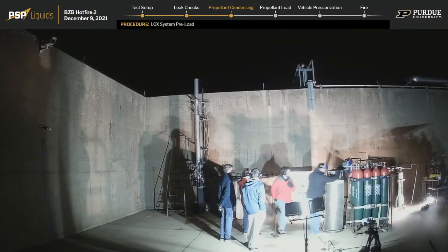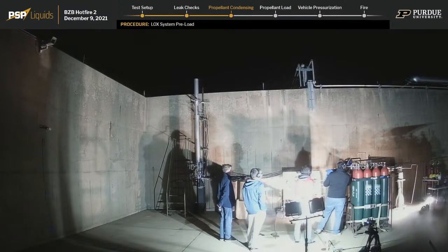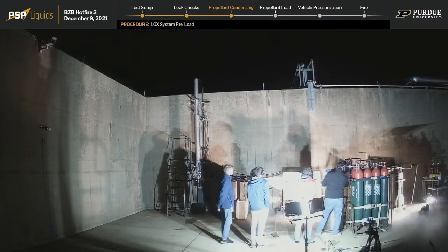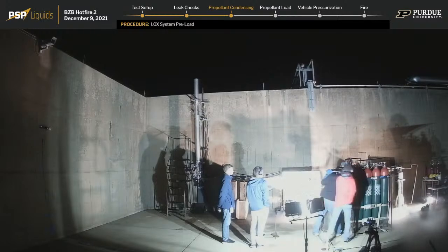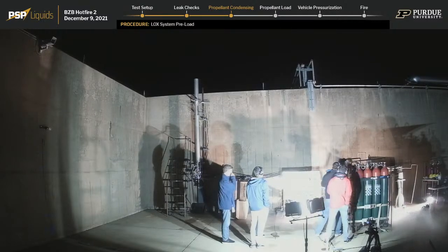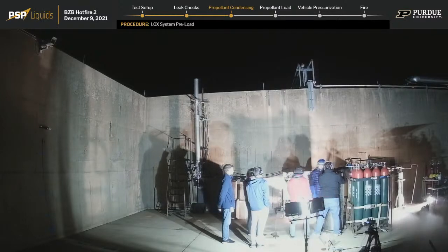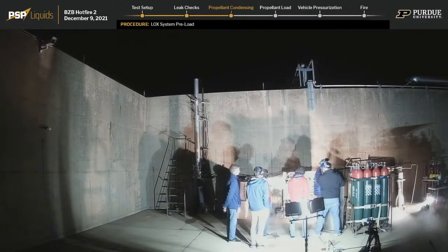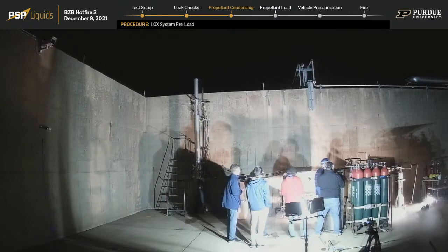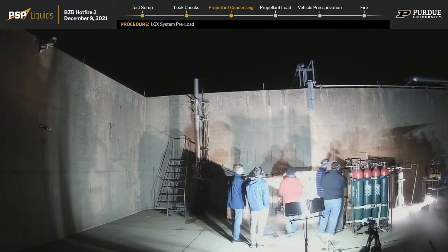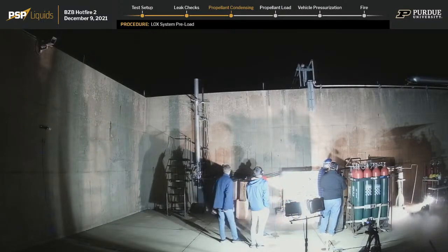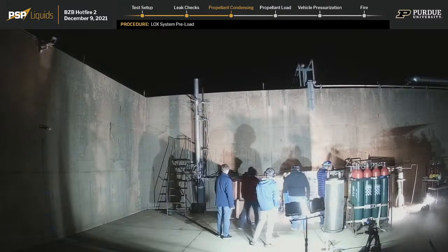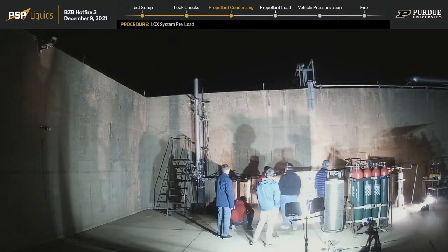Of course, it is no longer Halloween, but the mist of nitrogen is flowing over us. You can see we've dumped a good amount of nitrogen. 75 psi. For operations like this, we wish they were indoor, just from a temperature perspective. But in this environment, what are some of the dangers you can have with indoor operations with gaseous stuff? Yeah, not even with an indoor operation, but in any kind of enclosed space, there is a danger presented by having non-oxygen inert gases close to operators. So we're very mindful of that and need to make sure that our operators are actually intaking oxygen and are not suffocating.